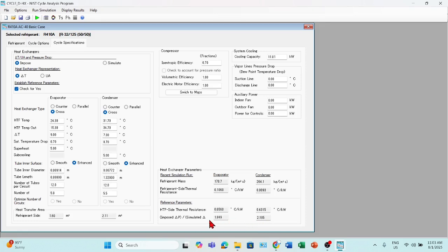These values are usually greater than 1, which means that our experimental result has more pressure drop compared to our simulated pressure drop, because in the experimental results we have also considered the U bends in the configuration, whereas in the simulated results we don't consider the U bends for the double pipe heat exchangers.